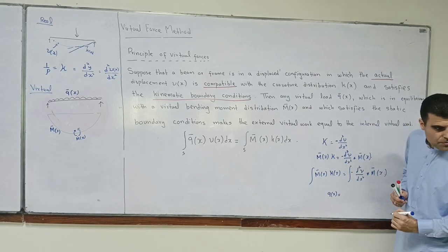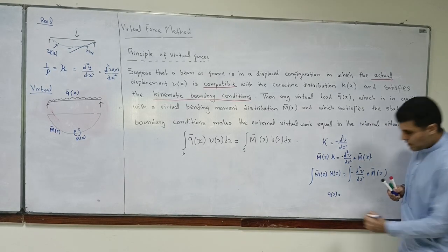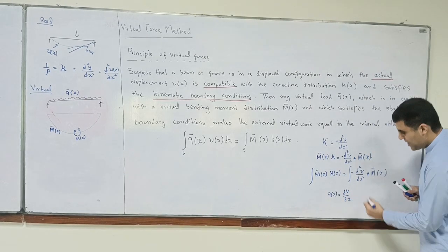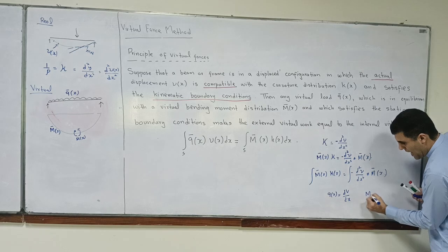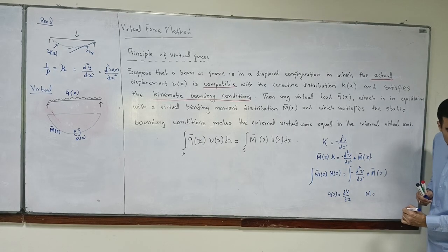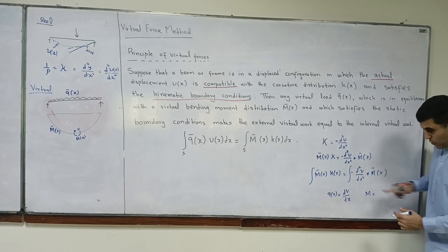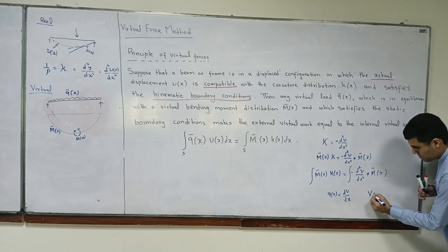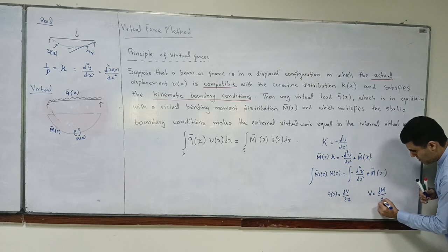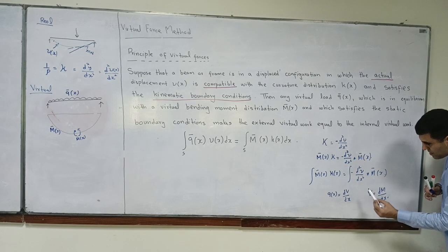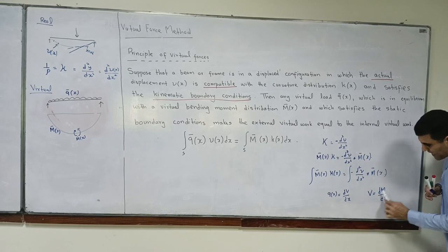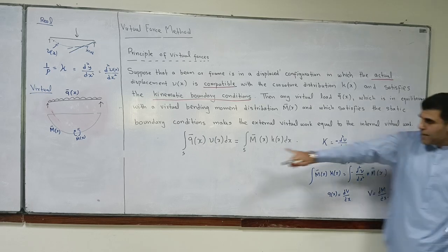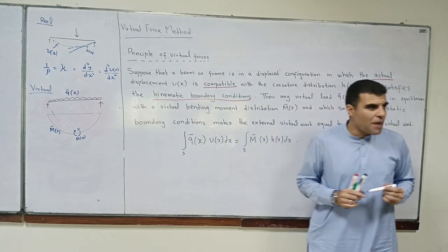What is it equal to? dV by dx, and V is dM by dx. So this we can put over here and we can get d2m by dx squared. So that also you can put over here. That's why you get it in terms of q bar x.